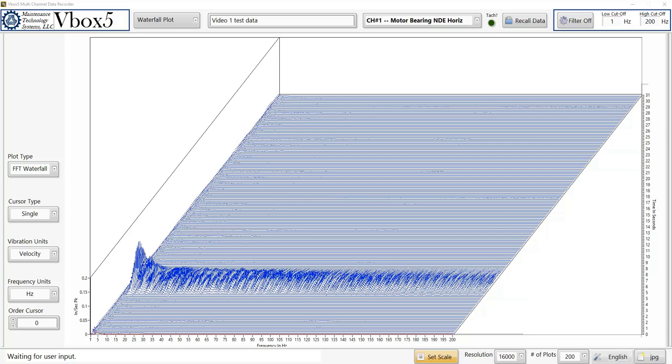And if you notice, we've got a little red arrow here. If I click part way up through here, it will bring that cursor and it will overlay the data that's actually at that point. Note also that I've got a vertical cursor that I can move over if it will come up. There we go. And it shows me kind of the same frequency across the spectrum. So a little bit of cursor capability here on our waterfall spectrum. So that's basically the use of the different plots.